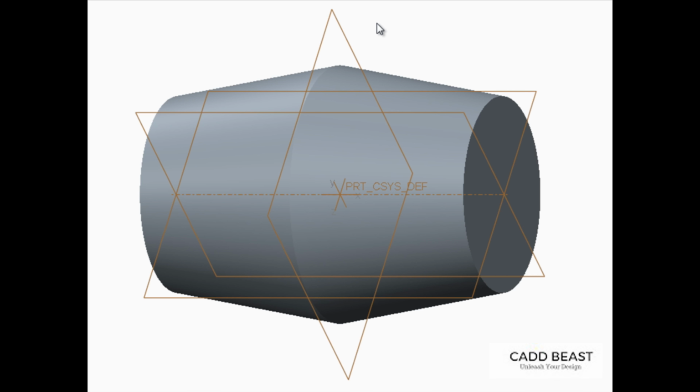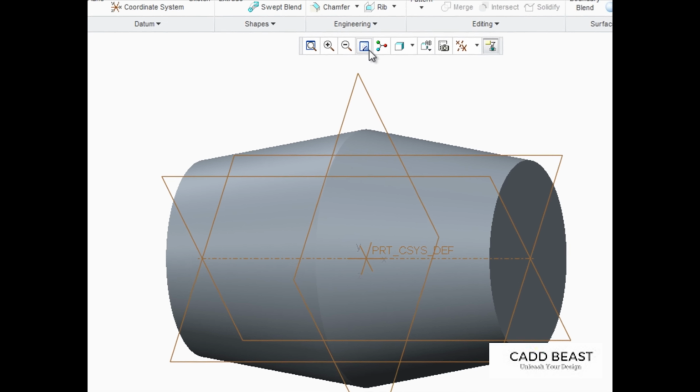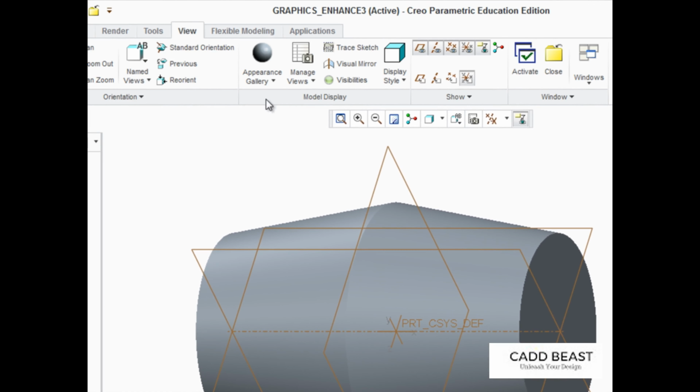You can find the name of any feature by moving your cursor over it, and when the feature pre-highlights, its name will be displayed. To turn the display of datum tags back on, go to the View tab, and in the Show Group, you can toggle the display on and off.